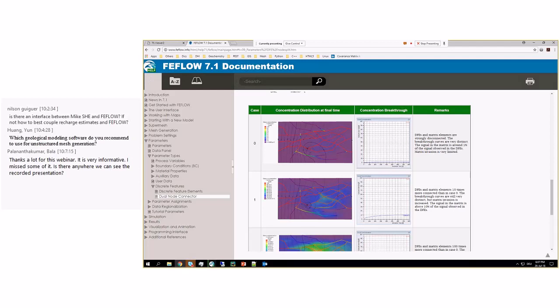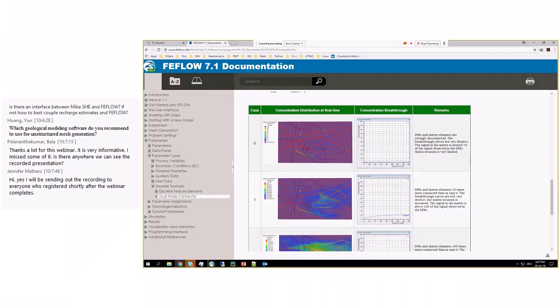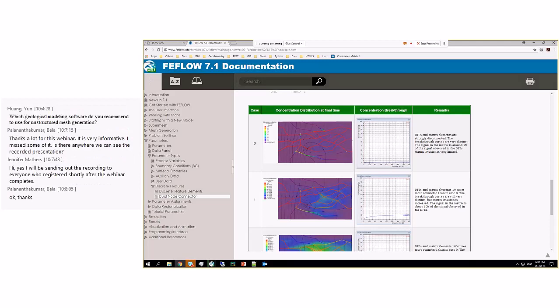Yes, I'll tell you, we have interoperability with GoCAD, GeoModeler 3D, and Leapfrog. All of them can provide input to FEFLOW. But all of them can also fail, because the typical workflow in geological modeling is that they can do very nice interpolation, fill, create different volumes, etc. But some of these can fail in cases where they have to triangulate the context of your geological systems or units, no? And this triangulation is read by FEFLOW and we use it as a constraint for the 3D mesh.